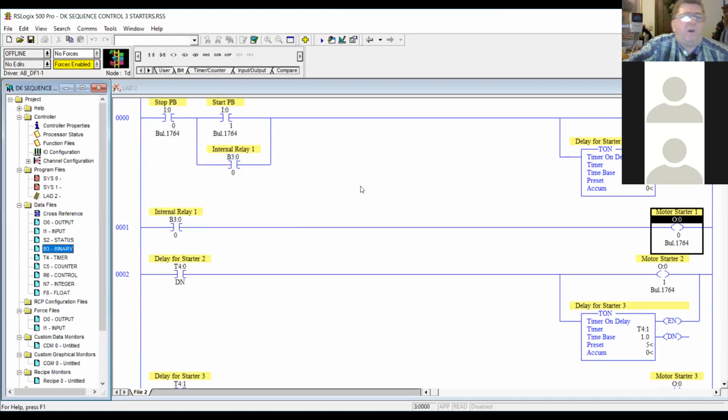And there are programs at Smithfield Packard and a lot of plants that use internal logic to do functions before a real output is ever turned on. There's no point in me trying to elaborate on that. All you want to see is when you see an address that says B3 anything, you simply know that it's an internal relay in the program that's not a physical relay. It's not a physical output. Does that make sense?